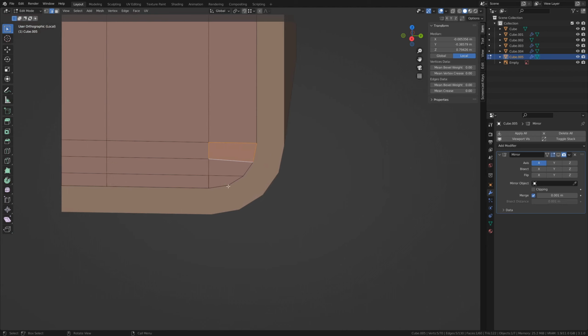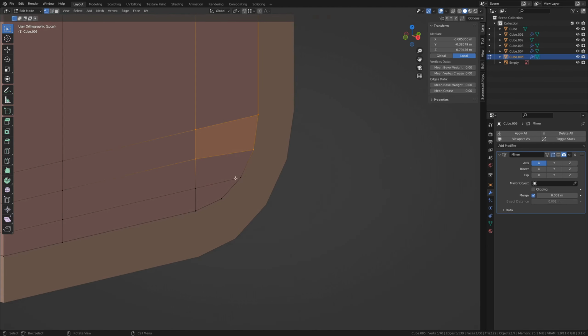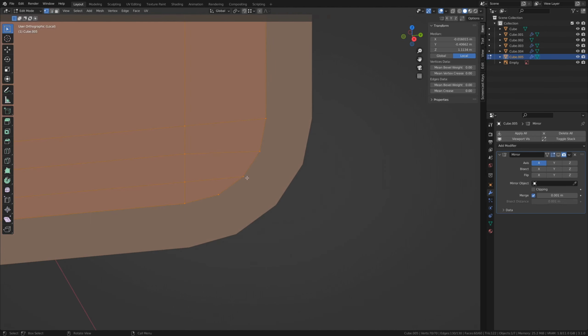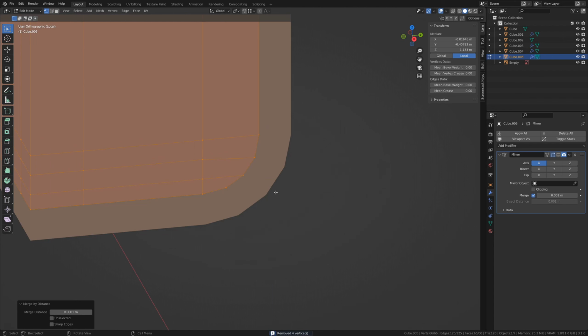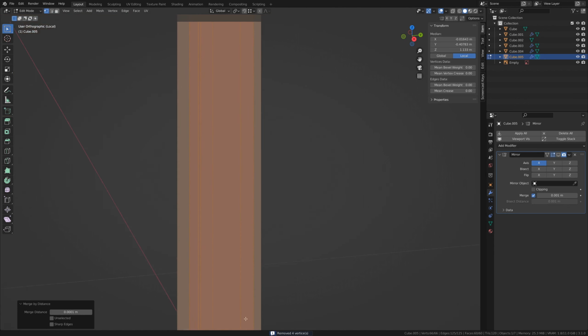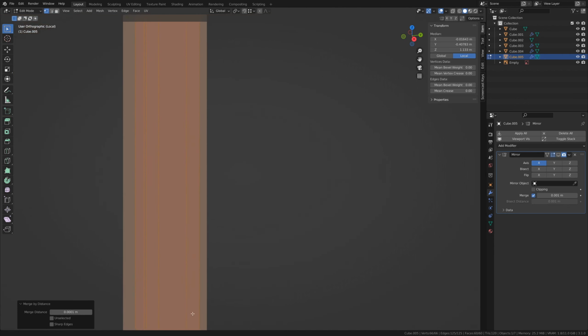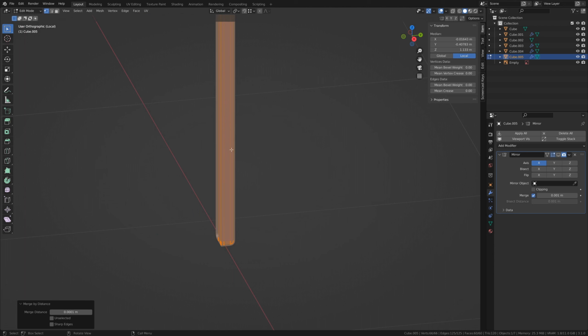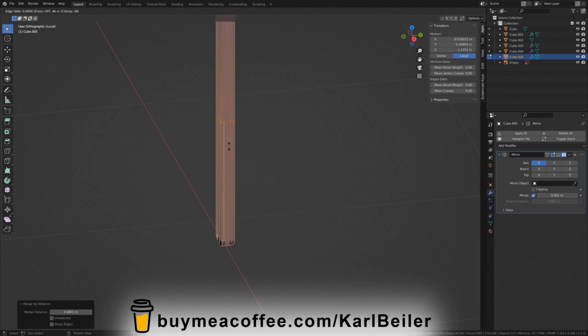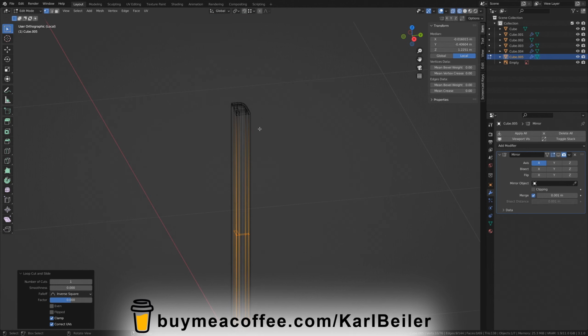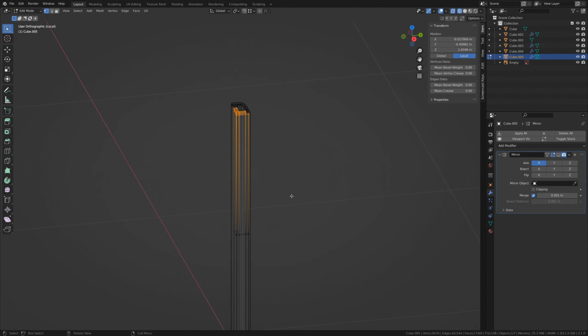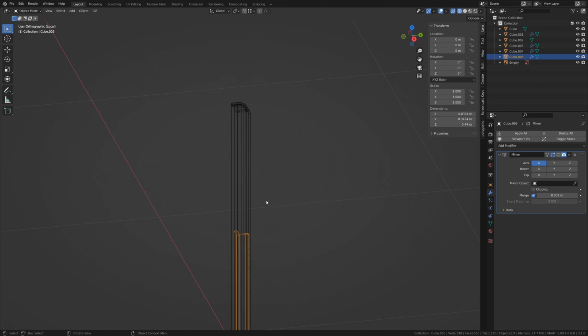And once again, we're going to have overlapping geometry, so go into vertex selection mode, select all, and merge by distance. You'll see down here it removed 4 vertices. Go ahead and do the same thing on the top, or to save time, we can cut right across the middle, hit enter or double click, whichever is easiest for you. Select all of the top vertices and delete them.